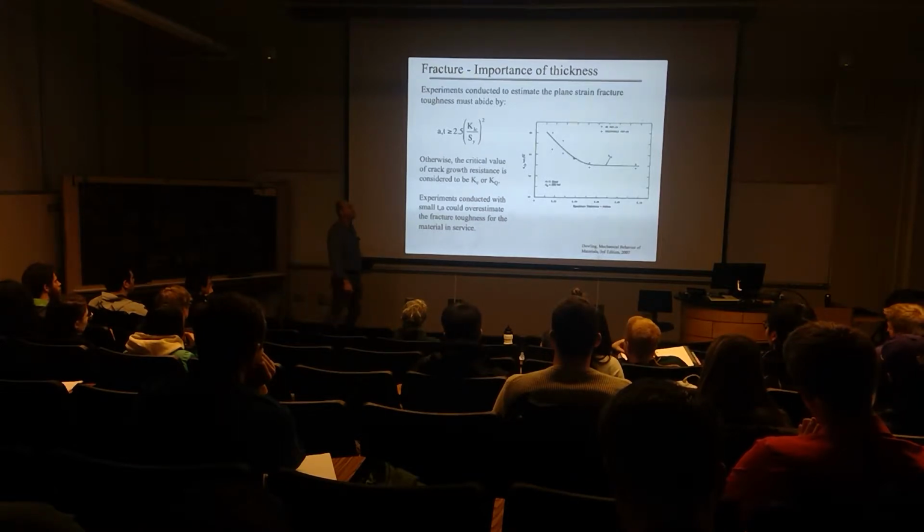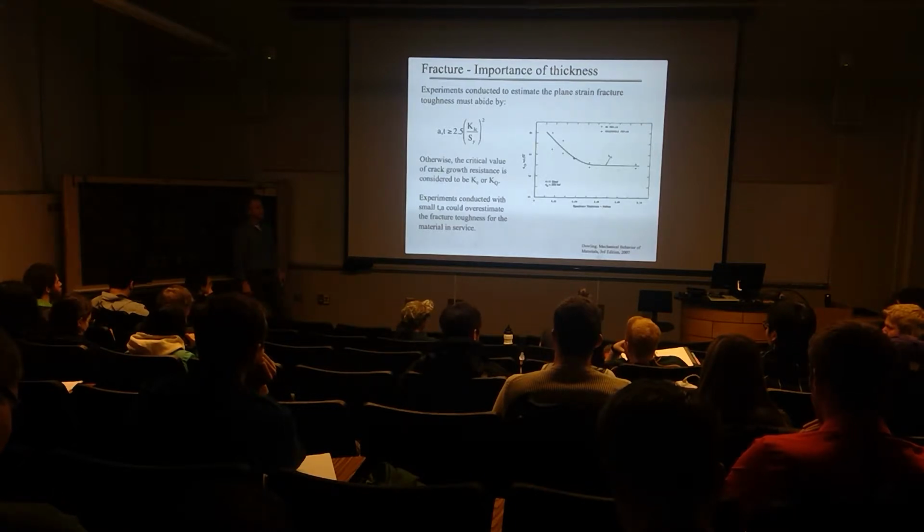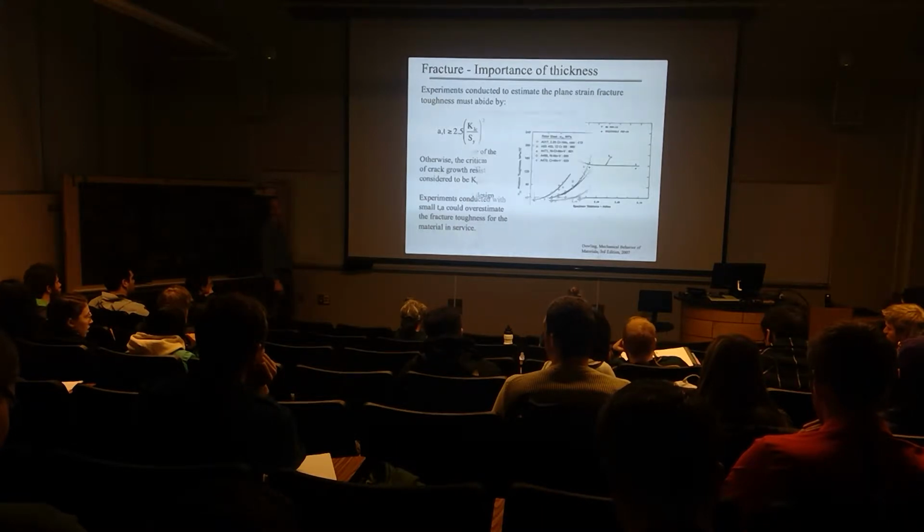No, this is about the crack initiation. The initiation of the crack and sort of the developing from a notch that's sawn in order to be able to have the shape. And then its progression is something that's still maintained or required to be very brittle. The pop-in event is a transition from a sawed-in notch and the apparent crack that we can develop by experimental protocols, and that which is really true of an infinitesimally sharp crack with no release of curvature.